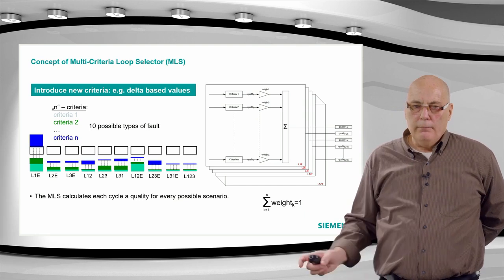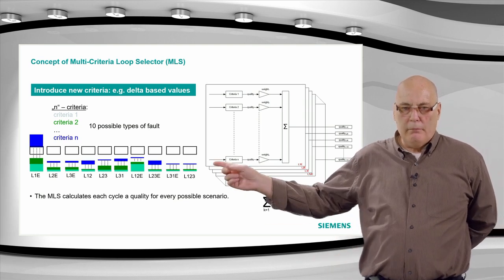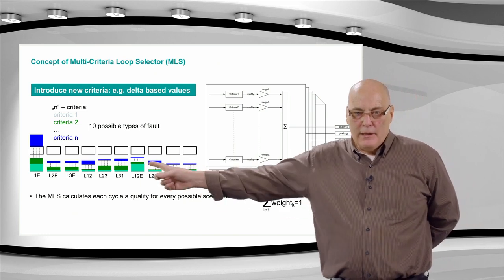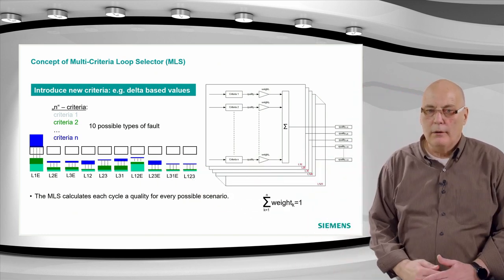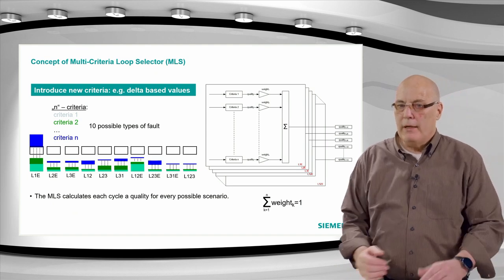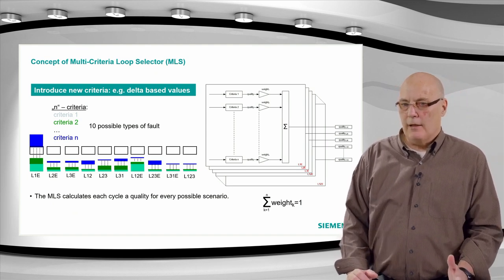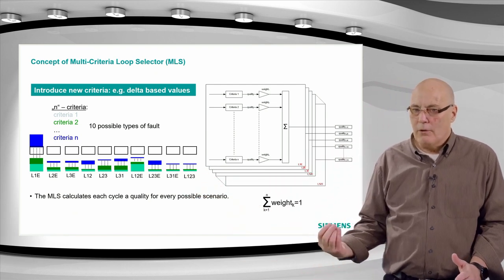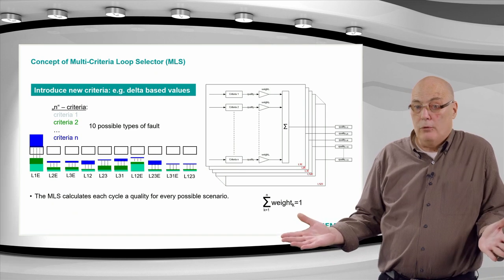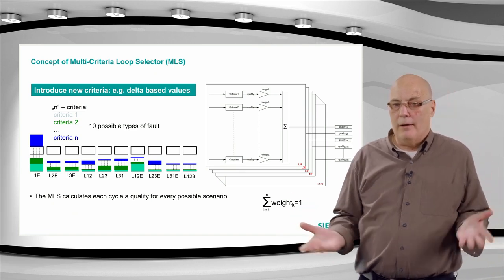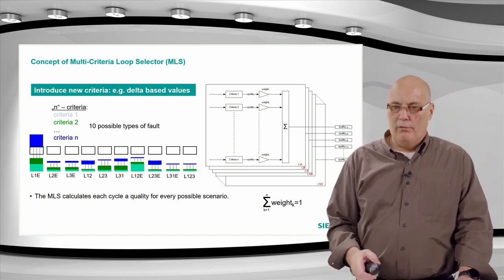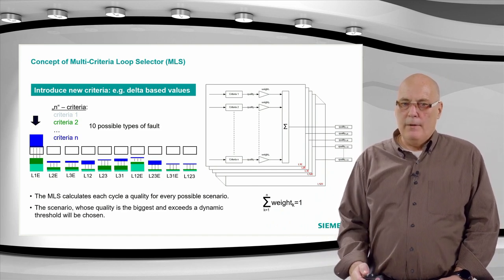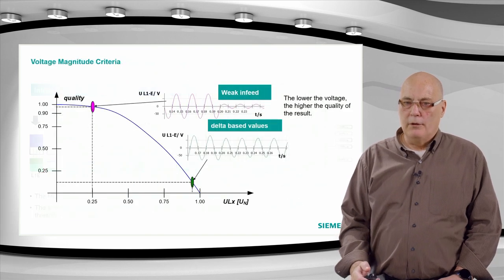So in this example, all the criteria or all the loops get some weighting, but it's clearly in this example complete left-hand side. The L1 to ground has got the highest, by far the biggest magnitude, and the selection would clearly say, yes, it is an L1 to ground fault, because all the others see a little bit. Remember, an L2 to ground would also see some ground criteria. It's a ground fault, so it could be L2 to ground, but that's the only thing it has, is some ground current. Nothing else. The voltage and so on would not confirm that, so the L1 would be selected. But we'll see that maybe more effectively in a graphic form just now.